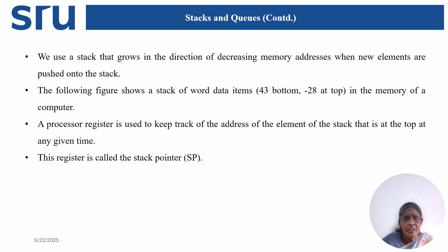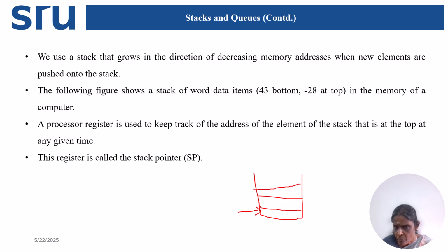We use a stack that grows in the direction of decreasing memory address when new elements are pushed into the stack. So what is the meaning? Pushed into the stack means data is filled here. The stack pointer will be here, because all are empty and this is the data filled.